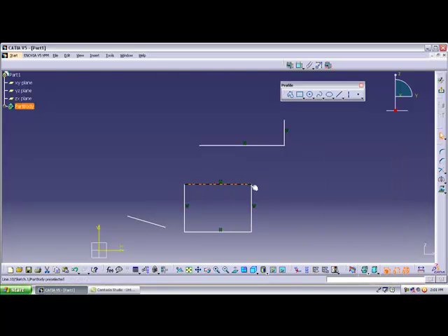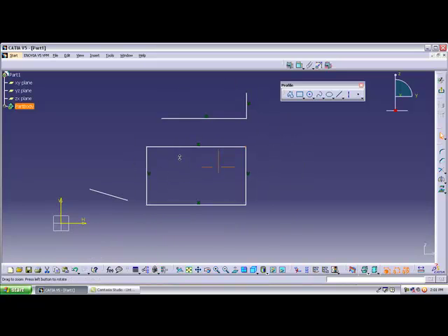See, right now the object is moving, meaning dimensions are varying, but we are locking. How are we locking? These two adjacent sides are compulsorily horizontal and vertical, 90 degrees. How can it be 90 degrees? One line should be vertical and one line should be horizontal. Like this we can make the geometrical constraints. Okay, these are the basic constraints, that is horizontal and vertical.